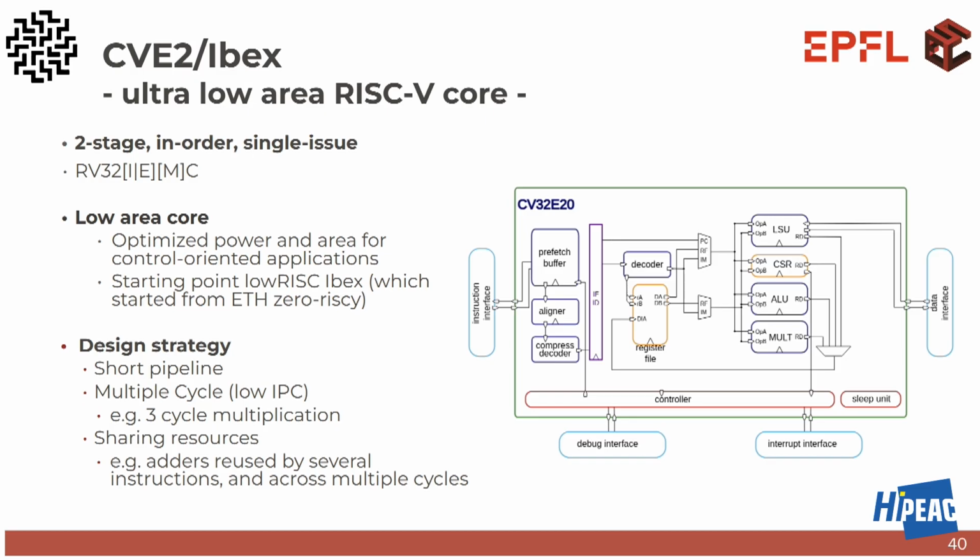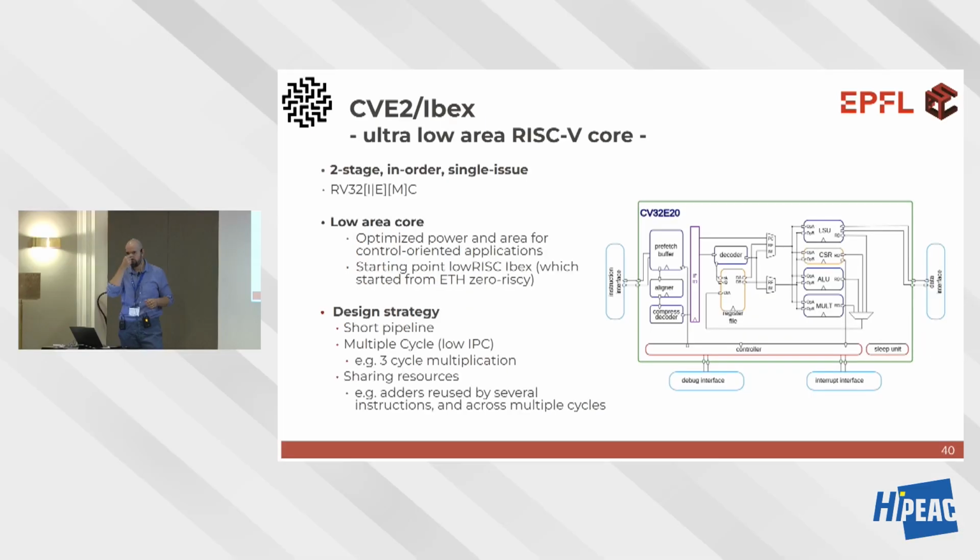So there is a big switch case, a very big switch case, that for each of the things decides what to do, and then the default case, so if none of them matches, it's an illegal instruction. If it is an illegal instruction, then the CPU traps to the illegal instruction routine. Some of you suggested using it to implement a software-based multiplier yesterday, for example, or you simply flood it to the operating system or whoever is running on your CPU, and that's it.